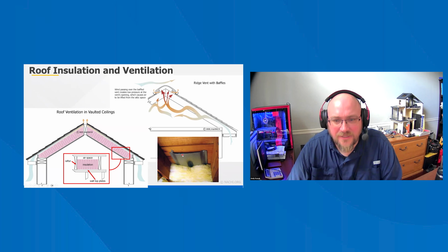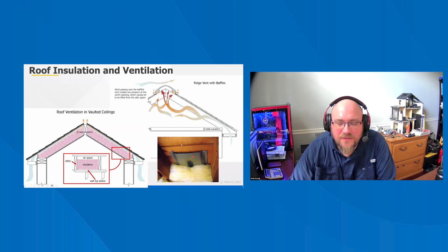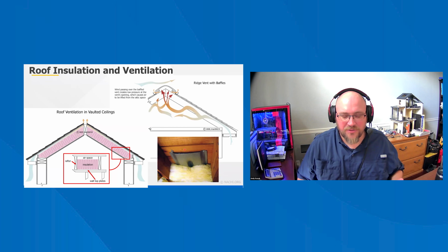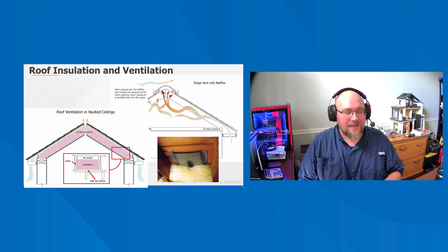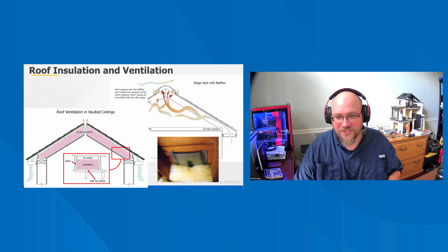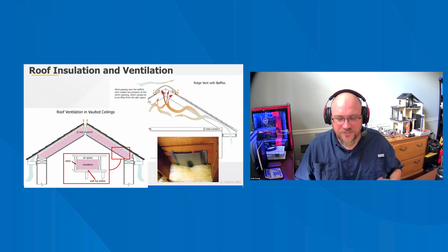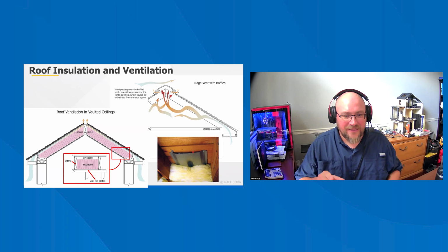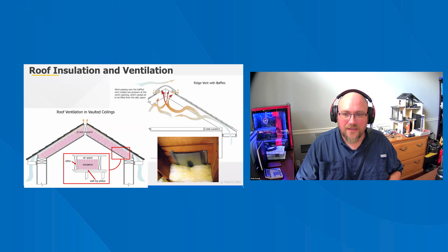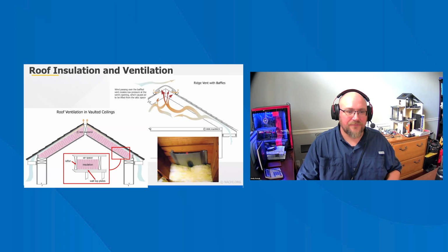Something that you'll see often, in this picture of the baffle on the bottom right corner, is that an insulation installer, especially if they're using blown-in insulation, if they're not careful, a lot of times they'll blow insulation and block the baffle from ventilation. So, doing new construction insulation or basically any house that has baffles installed, if you can see the baffle, I would definitely make sure that there is not insulation blocking that airspace that's coming through.